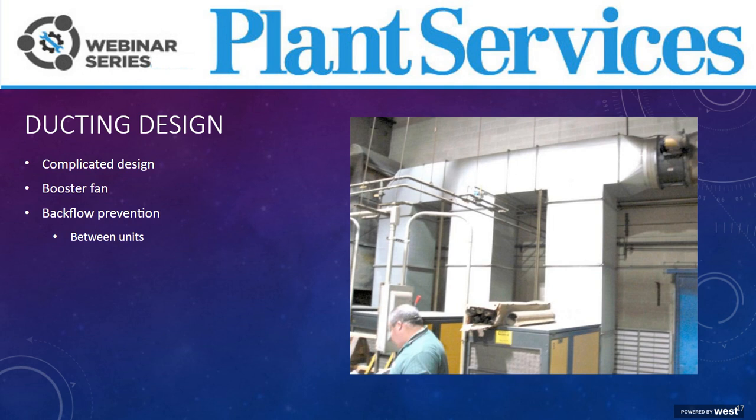What happens if, let's say, 2 of the compressors are offline, not running whatsoever, and only 1 compressor is running? If there isn't a backflow damper on each of these compressors, there's the possibility of hot air from that 1 compressor that's on to feed the offline units, thereby increasing the likelihood of overheating for them. So booster fans will certainly help, but it shouldn't be the only protection that you're considering.